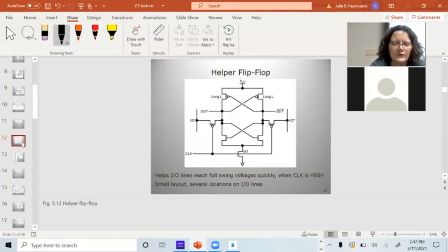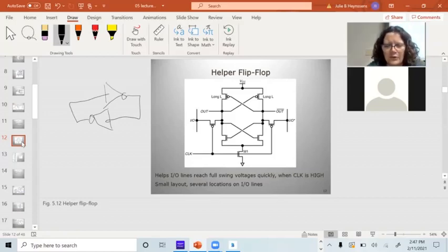If you take it to the gate level, what you have here is something wired up like this, and you have these 2 enable transistors here. It's enabled when the clock is low, because they're using the clock as an enable.